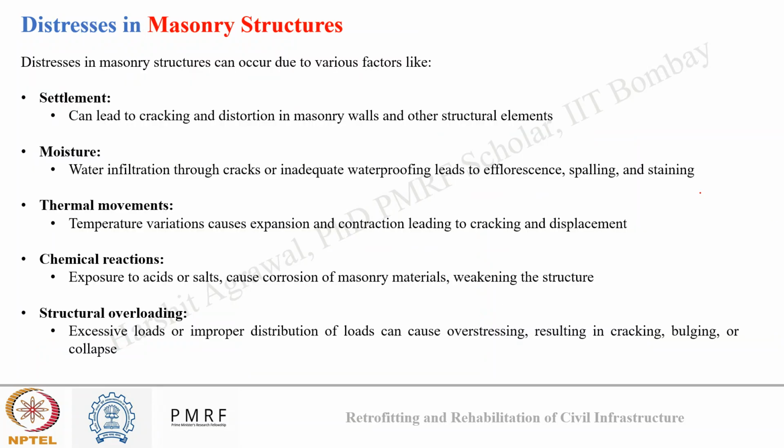Okay. Now, though masonry has been used for a long time and is often assumed to be more durable compared to concrete, it often undergoes distresses over time, and there can be several reasons behind the degradation. What are these reasons? These reasons include settlement of foundation beneath the masonry structure, which can lead to cracking and distortion in masonry walls.